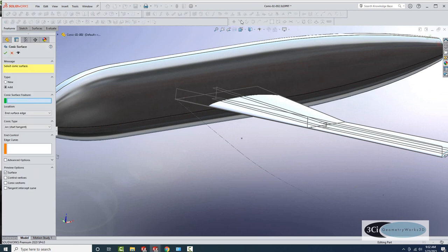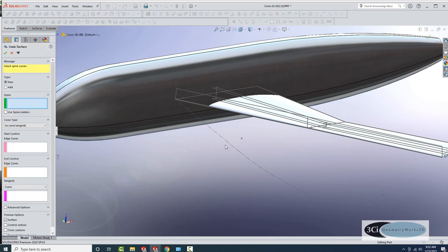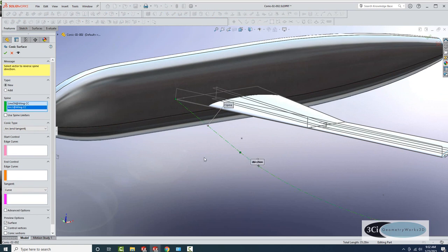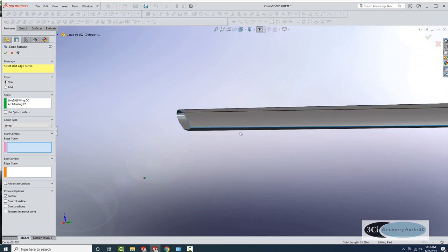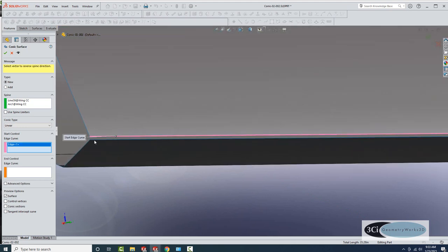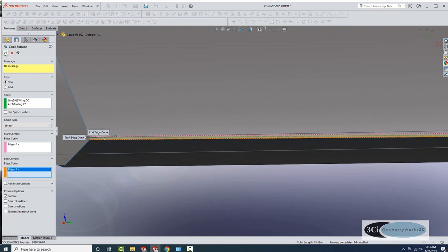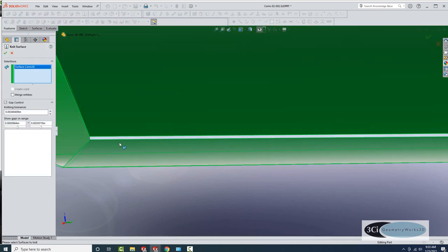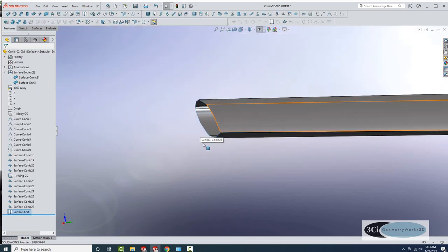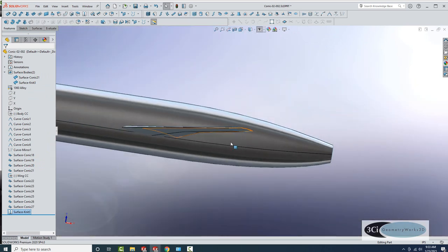So now we're going to add the trailing edge, which is a vertical surface between the upper and lower edges of the aft of the wing, where we'll use a linear. This is a new conic surface and does not have the same spine as the old one, so we establish a new one. As a rule, it's always best to use the edges of the previous surface so that you have less tolerances between the bay we just built and the surface before. Now we trim up and make it work.